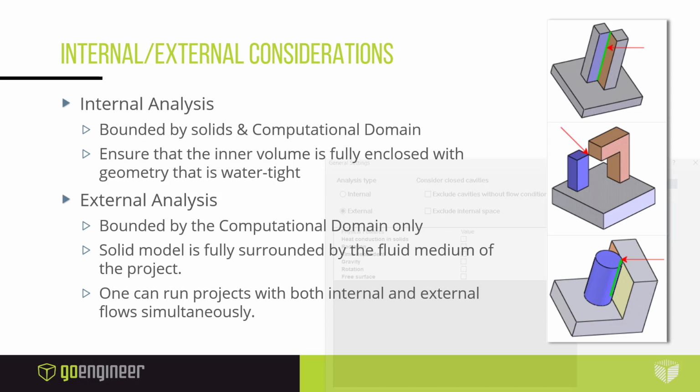Ensure that you're enclosing your volumes with solid bodies that are coinciding face to face or have a bit of volume interference. Any coinciding entities that involve edges or points will potentially be seen as an opening since we're operating within the SOLIDWORKS ecosystem. If you require the calculation of fluid flow around your model, it's best to choose the external analysis type for this.